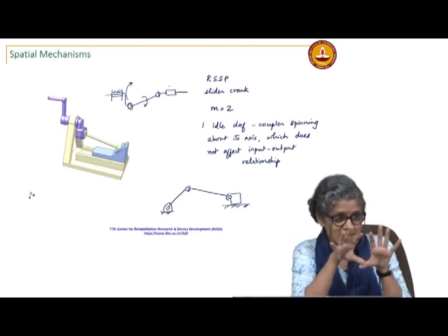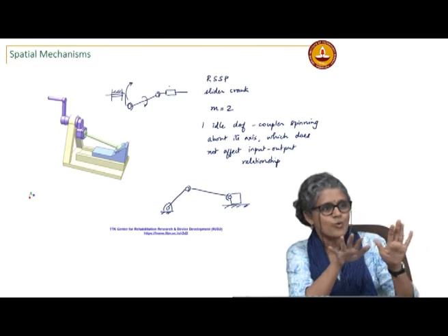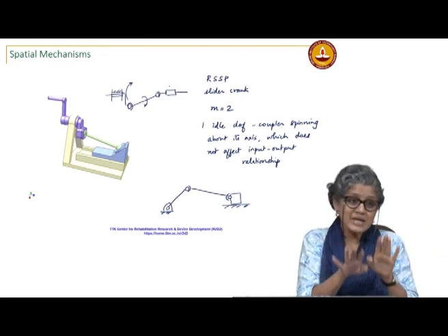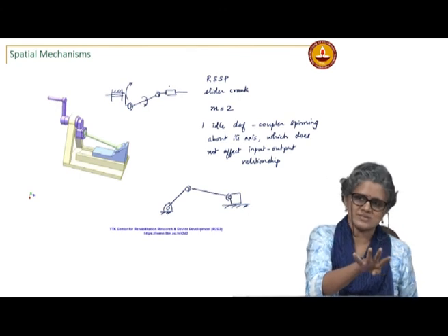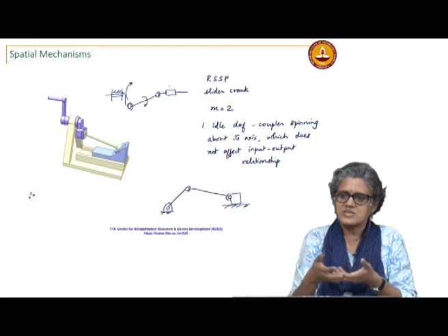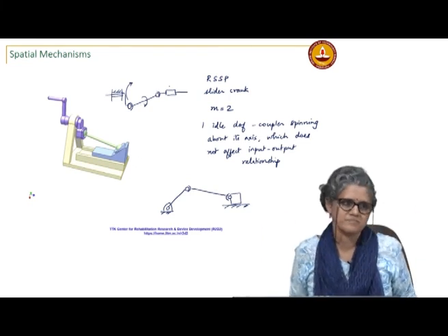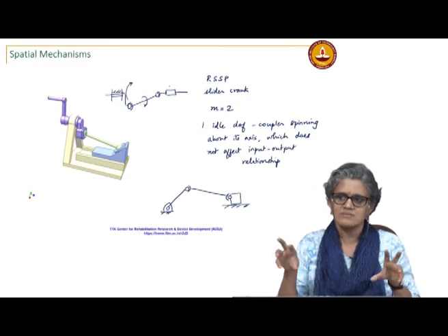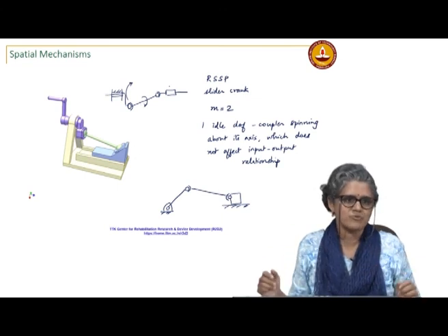We very clearly define the conditions in which Grubler's criterion applies. Then you need a minimum of 4 links. If I want higher pairs, a cam and follower and the fixed link make a 3-link mechanism, with the fixed pivots for the cam and the follower to rotate about.